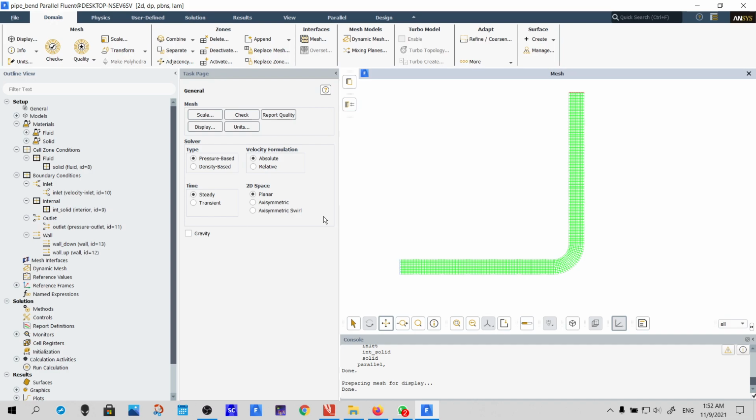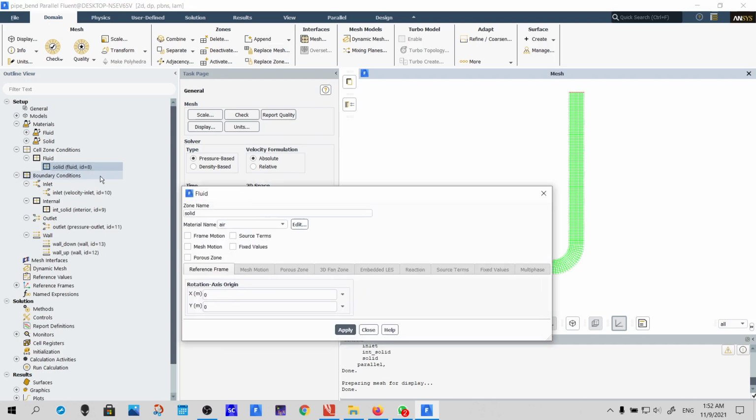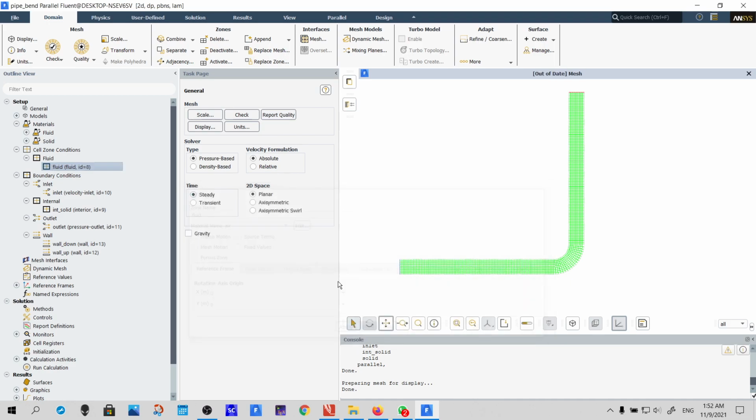If it doesn't get selected, if it is set as solid, the type is fluid, the name only is solid, because initially we selected the 3D bounding box as a solid. We didn't change over there to fluid. So the name you give there gets here. You can simply edit this. You can give some better name. Maybe you can say fluid. Apply, and then click over close.